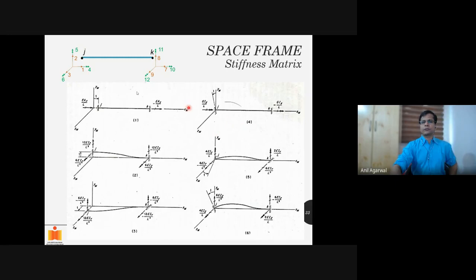Likewise, for the 4th degree of freedom, that is this twisting or torsion, we are introducing a coefficient called Ix, or the torsional constant. You might be familiar with this term, torsional constant, which somehow, by some magic, incorporates all possible torsional rigidities of the member. I don't want to deal with that problem seriously; I just want to simplify that issue. So we bring in a torsional constant, assuming that there are no warping issues and it's all behaving perfectly.